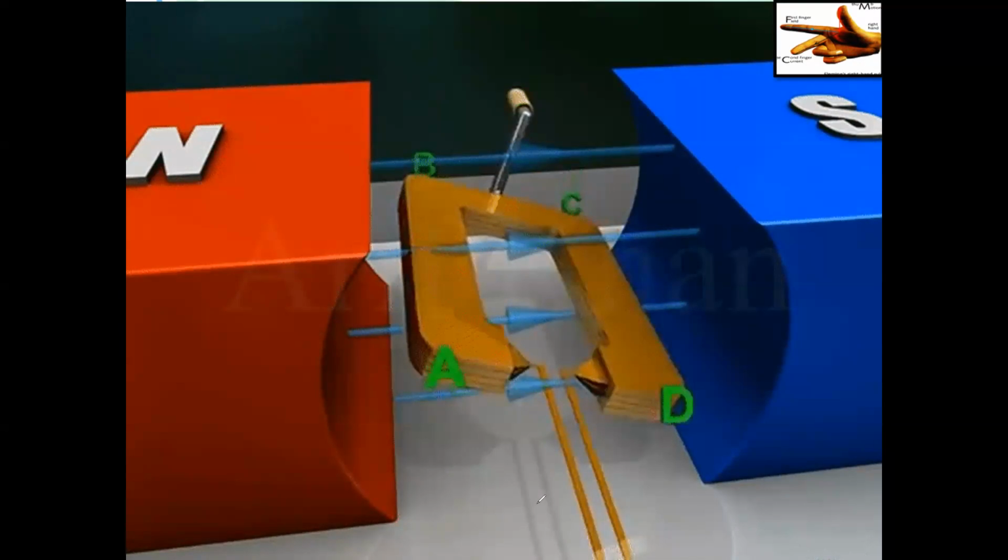To find the direction of induced EMF, we have already discussed Fleming's right-hand rule. According to Fleming's right-hand rule, your index finger, your first finger, should point in the direction of the magnetic field. Your thumb represents the rotation or movement of the wire. And your second finger automatically represents the direction in which there will be an induced current. So, for example,